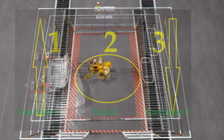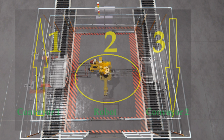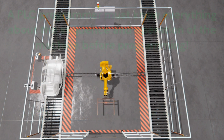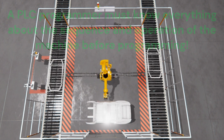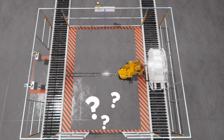Conveyor 2 sequence will allow an empty carrier to enter the inspection station. If the robot places a car body onto the carrier and returns to the home position, the carrier with the defective car body will exit the inspection station. A PLC programmer must know everything about the sequence and operation of the machine before programming. Ask questions or view existing documentation to ensure you know the logical steps to the machine's operation.